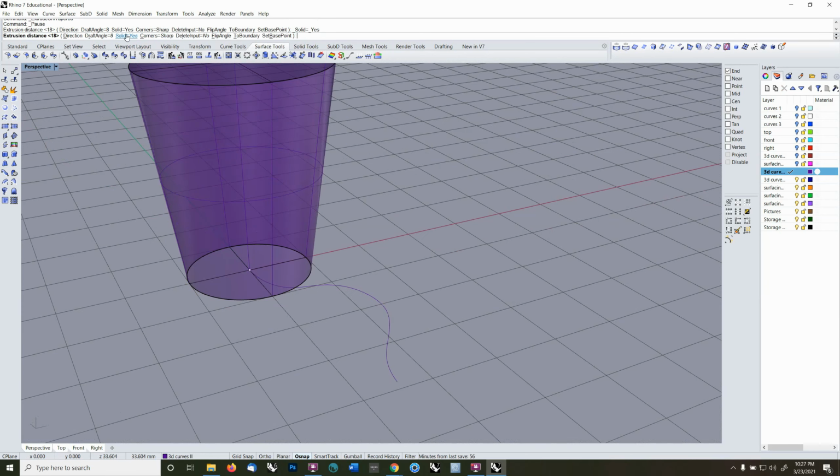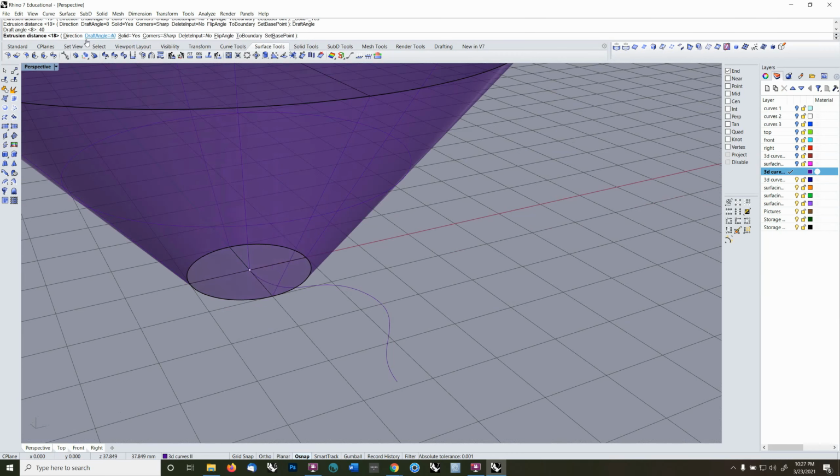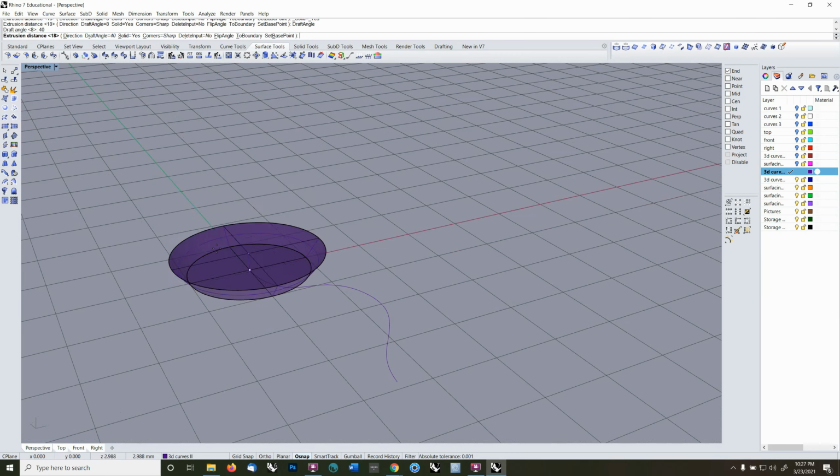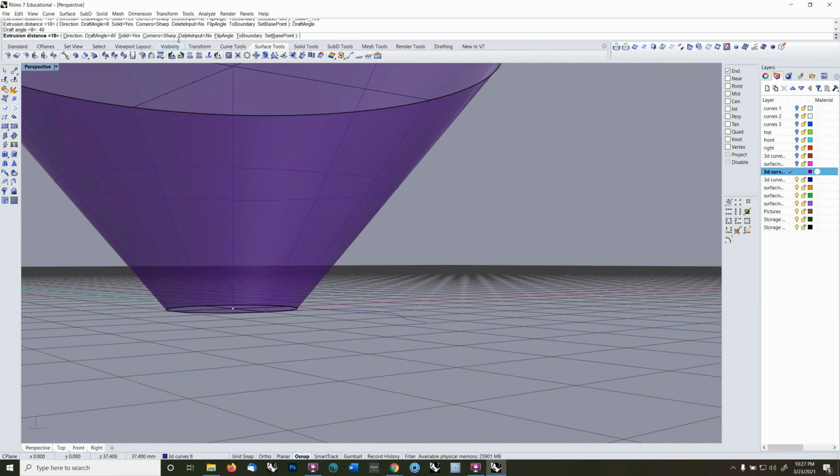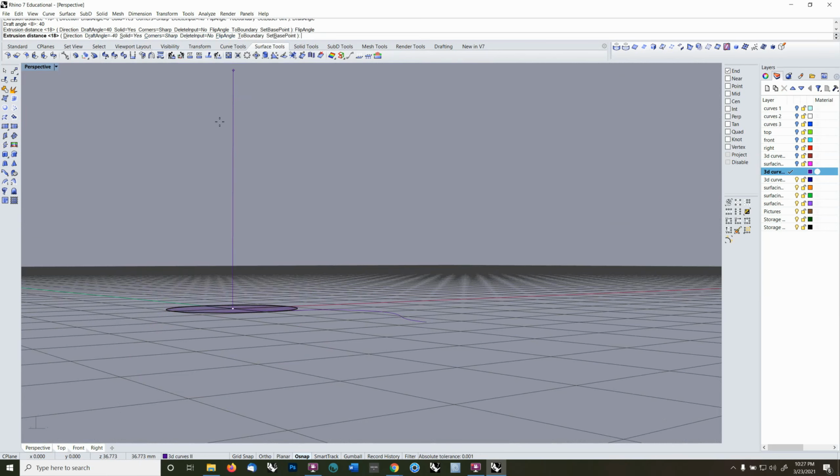And usually what you want to change when you're doing this is the draft angle. To change draft angle, you have to actually click on draft angle. And then you can type a number in there to make it whatever angle you want. You see it flips directions as you go past the curve. If this isn't the direction you want and you want the other direction, you can hit flip angle or F, enter.